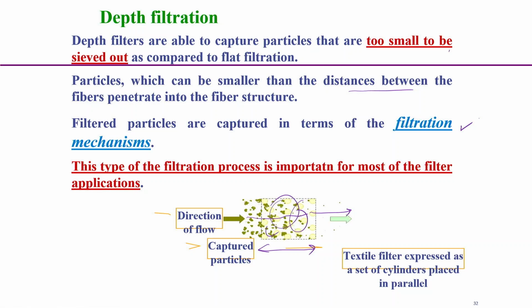This type of filtration process is important for most filter applications. For large particles we depend on surface filtration, and for depth filtration, where we are dealing with very small particles, we cannot produce a fabric with a very narrow pore size, because it will enhance the air pressure, so the pressure drop will increase.